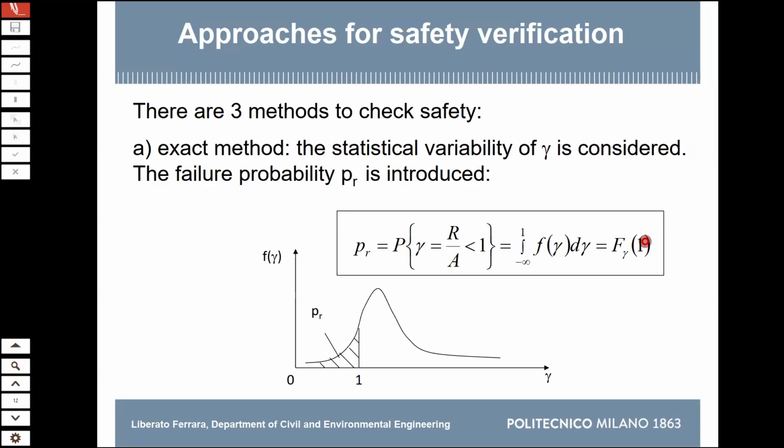Well, it's true that it's rare to have this, but one thing in precast structures is that we do not have the possibility to really go for this full approach, but we can have something like that. As I was telling you the day before yesterday, precast factories, especially for what they call special products like roof elements with strange shapes, must make regular load-bearing tests up to failure of their element once a year.